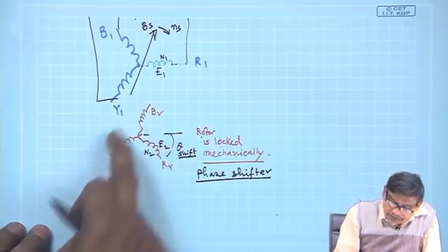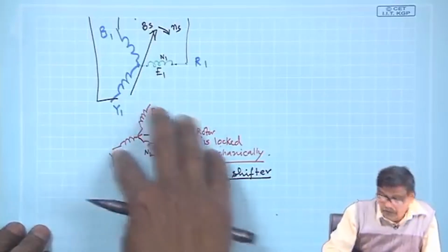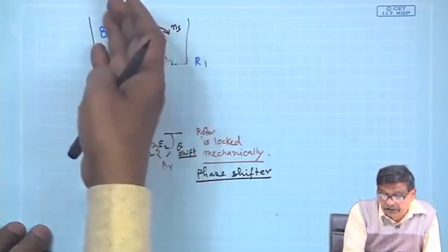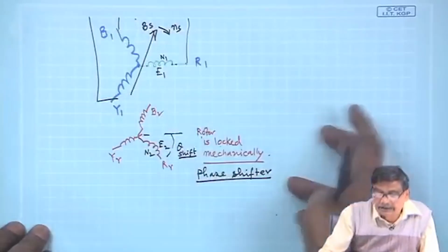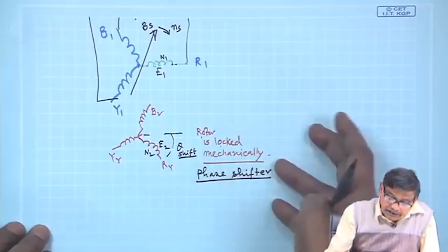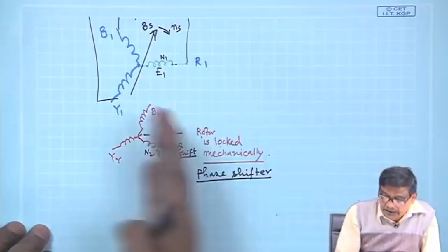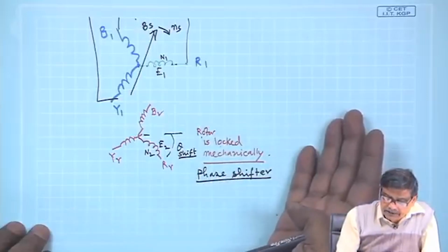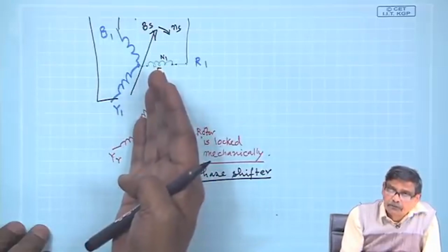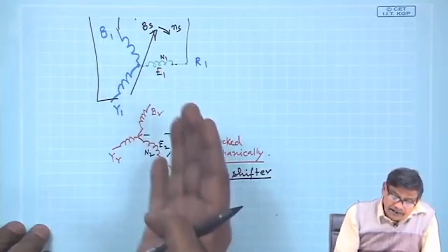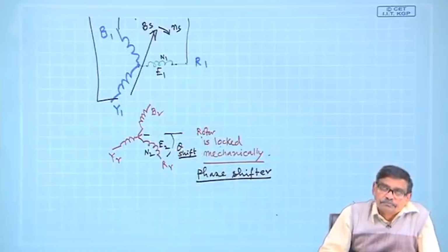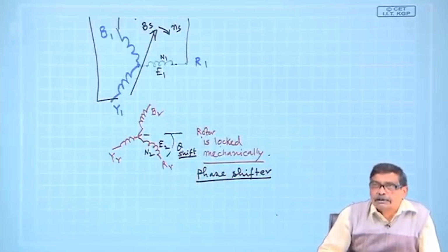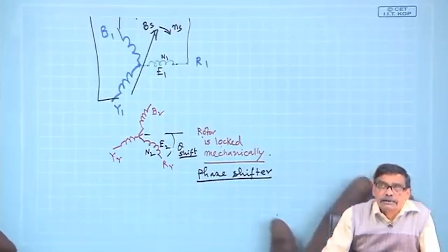So, when will balanced 3-phase current flow? When you load it. For some purpose you have changed the level of voltage and phase shifted it with respect to the supply voltage, then it is to be connected to some load. The moment you connect load like a transformer secondary, currents will flow, and with a balanced 3-phase load, let us hope balanced 3-phase current will flow. The moment it carries balanced 3-phase current, very nice things happen. Then this fellow too will produce a rotating magnetic field, and this we will discuss in my next lecture. Thank you.